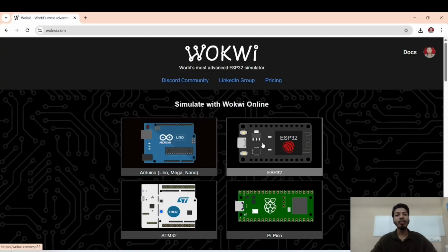In order to do this project, we will be using the Wokwi interface. For that, you have to come to wokwi.com, and this is the Wokwi website. This is a browser-based simulation where you will get different development boards and components, and you can connect them and build circuits so that you can simulate and see the results.